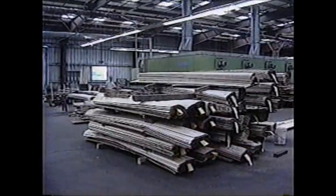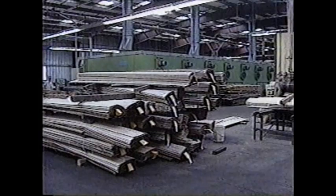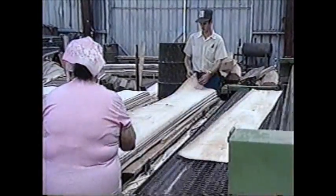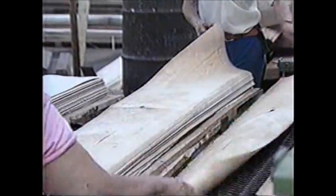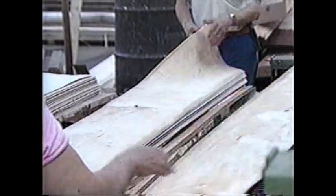The veneer resulting from a flitch is piled as a unit, tagged, and kept together. This allows matching for color and grain by the end user. The veneer, flitch by flitch, is put through a dryer about 100 feet in length. Depending upon wood species and veneer thickness, the trip can take from 1 to 17 minutes.